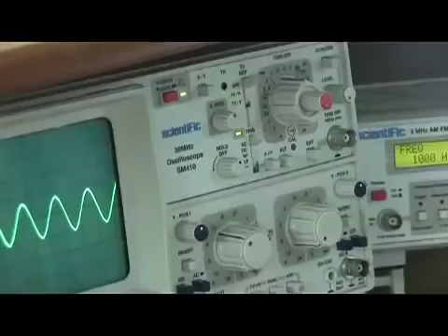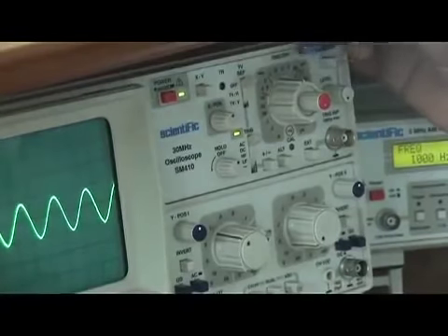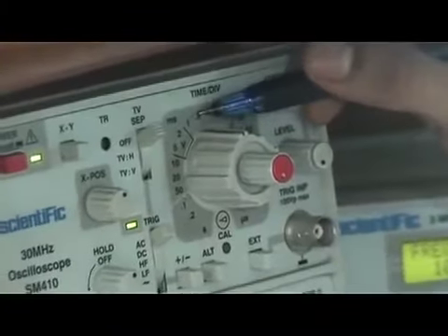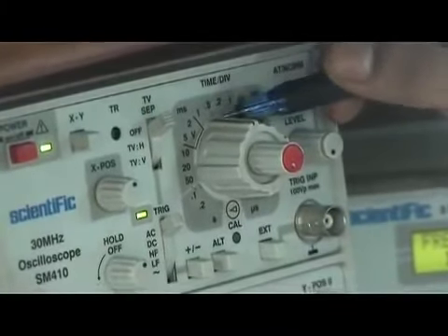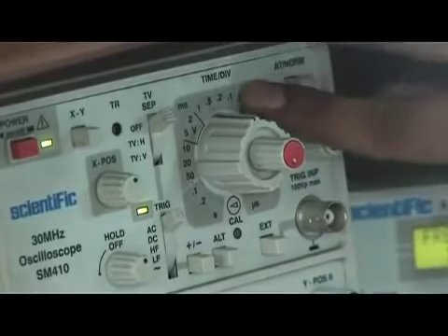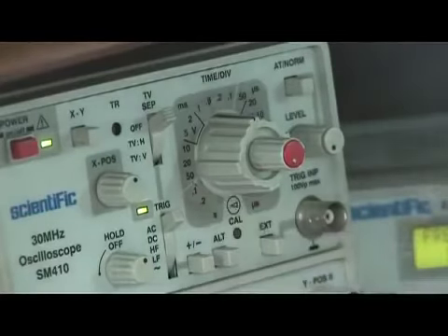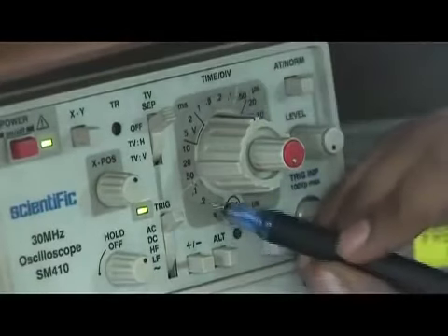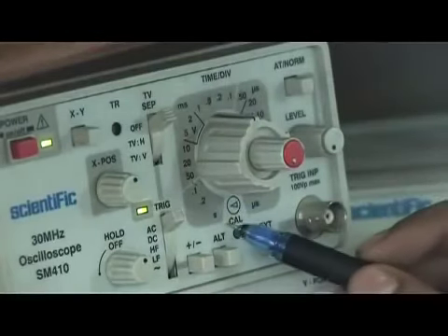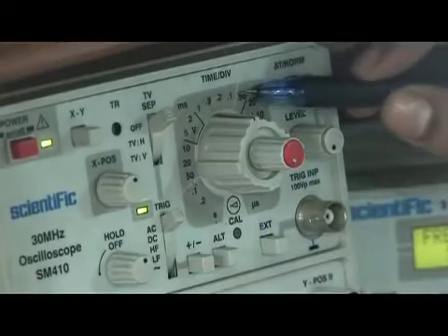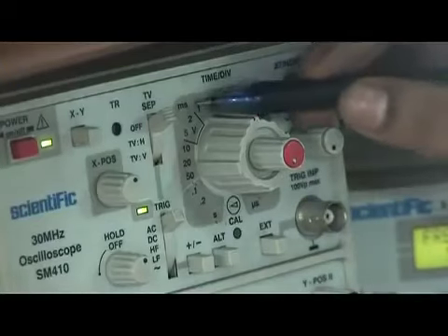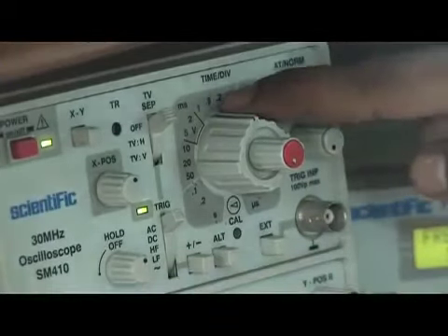So it is 2 into where this knob lies. See, there is a line here, and this lies at 0.5. So 2 into 0.5 is how much? 2 into 0.5 is 1. What will be the unit? From this small gap to the small gap here, the unit will be in milliseconds. From this gap to here, the unit will be in seconds. From this gap till here, the unit will be in microseconds. But right now we are in the range of milliseconds. That's why it is 2 into 0.5 milliseconds.